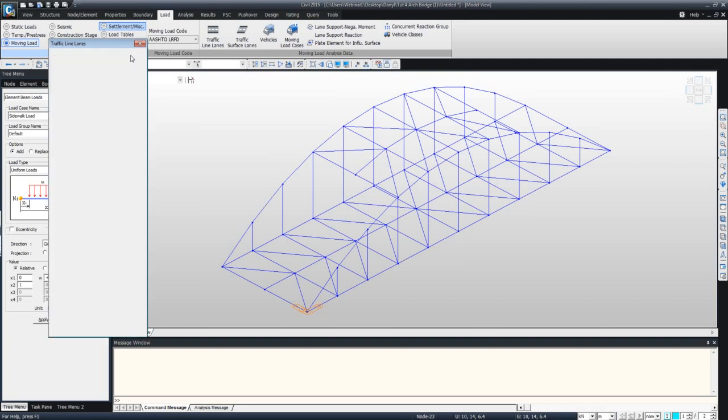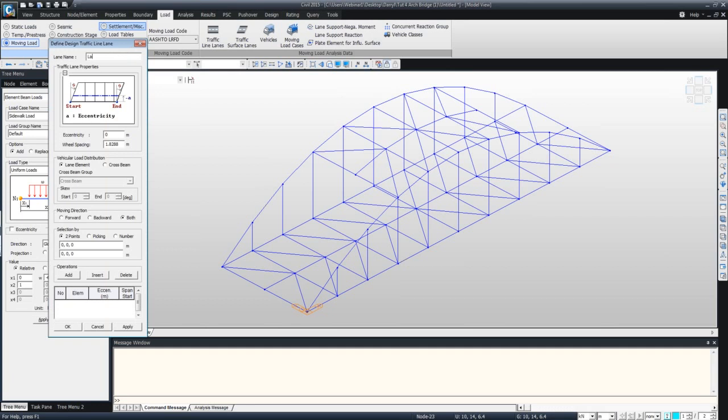So first let's enter lane 1. And actually, let's change the units to feet. What it'll be doing is you'll be selecting a certain reference point, and then from that reference point, this A parameter, that's just the eccentricity. So let's make this first lane -11.5. And I'll select crossbeam, so it'll do it with reference to these crossbeams I've created.